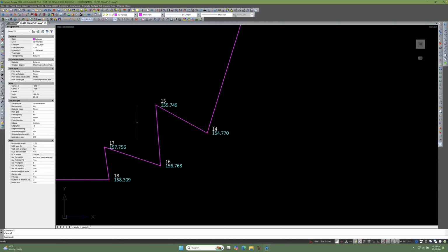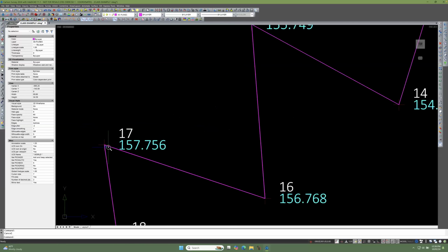Now, of course, they weren't aware of the linking switch at all. They didn't know anything about it, but his was set off. And so he's moving the point around thinking that it's not going to affect anything. Well, it's updating the coordinate file and it's updating the lines. And so these points are just real close together.